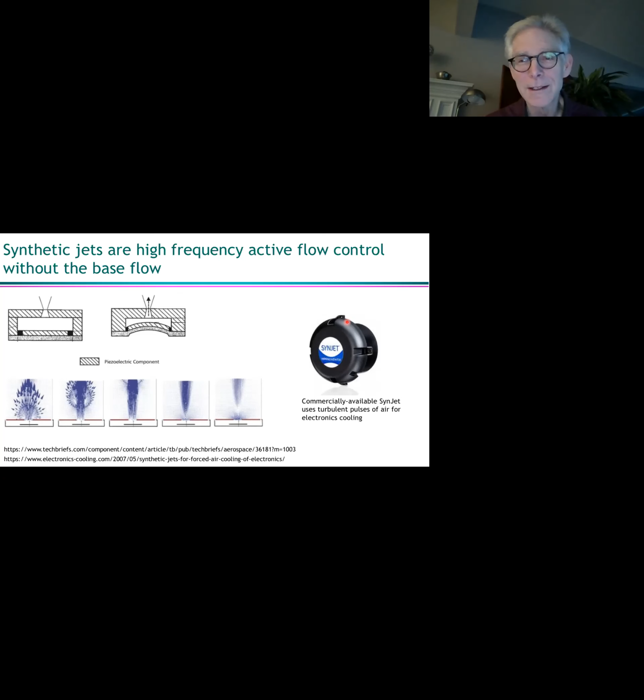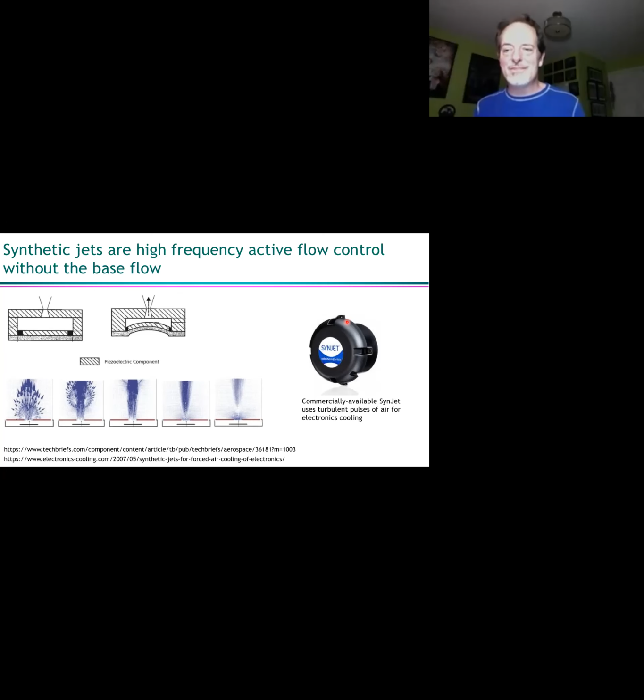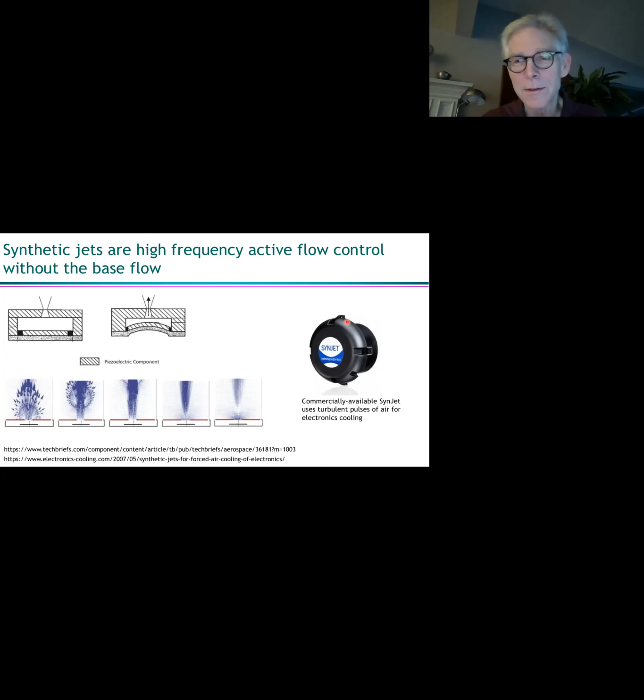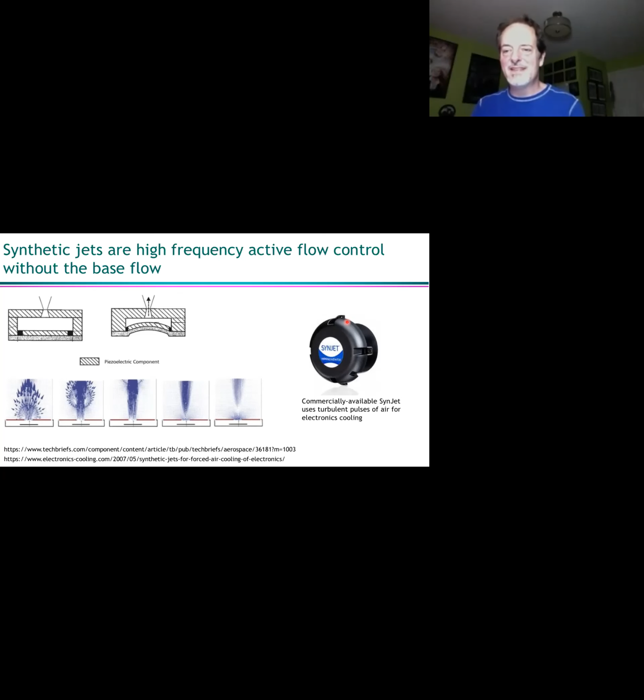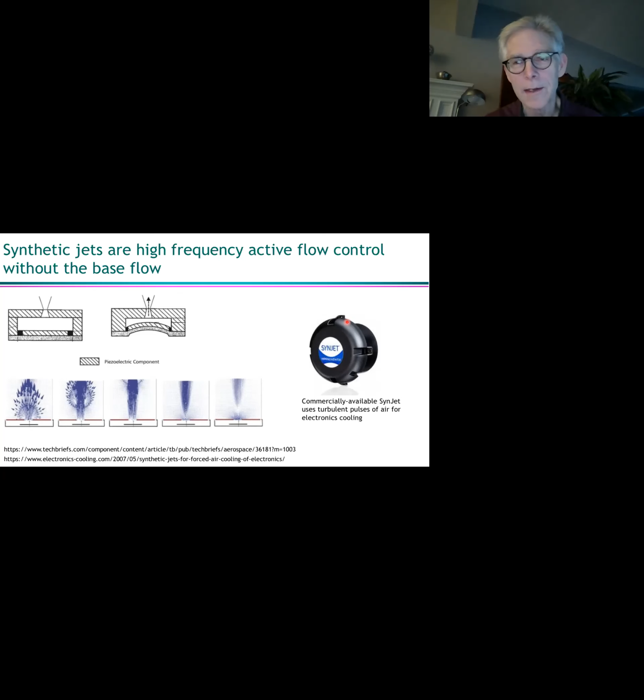Like crazy. And it turns out that the vortex shedding frequency of the fluid, which is seawater, was exactly the same as the natural frequency of the periscopes. Yep. So it cost millions of dollars to fix this. Then they couldn't really change the speeds of the periscopes and how far they came in and out of the sail. So they had to change the entire structure inside the sail to change the natural frequencies of the periscopes. Oh man.